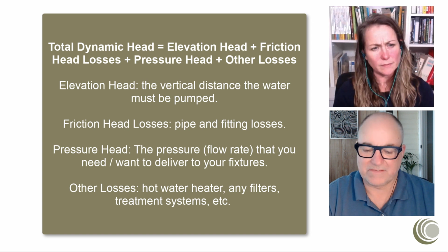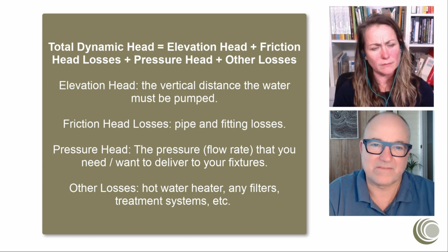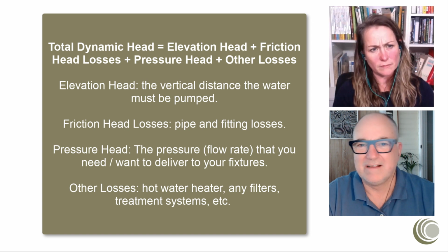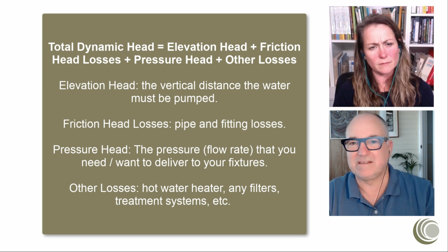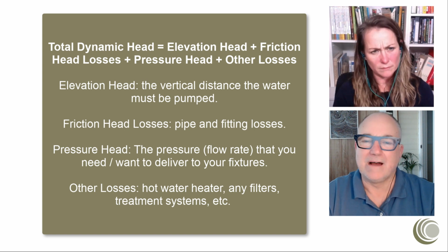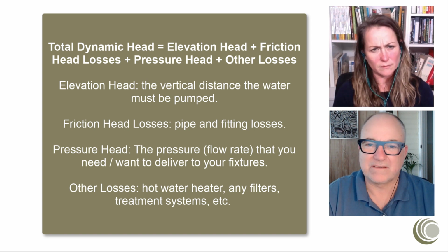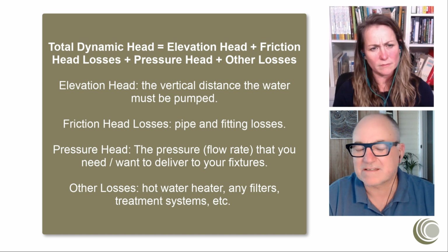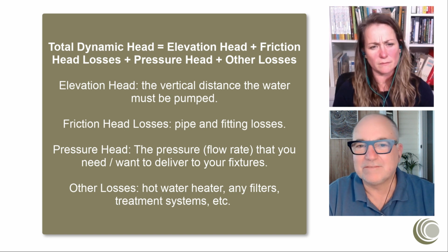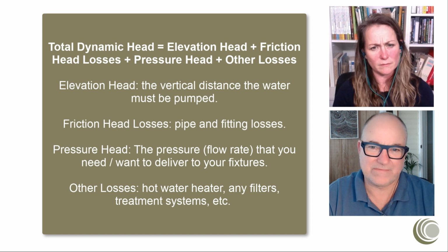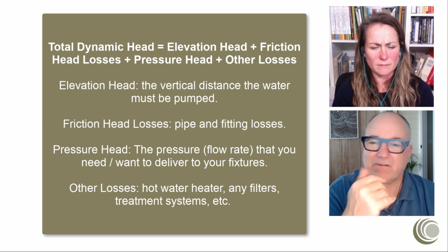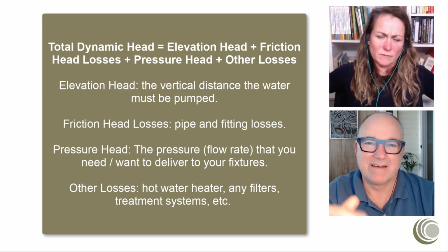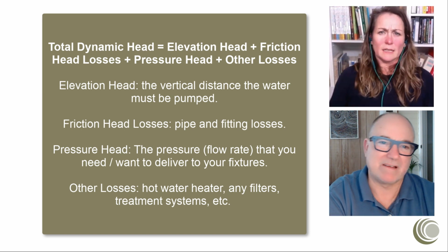Yeah, say you've got a garden variety pump that will give you 30 meters or 100 feet of head, but throughout your plumbing system, because of bends and friction losses, you lose 10% of that. You're down to 27 meters, if my maths is right. And if the highest supply point that you need to lift the water up to is 10 meters above it, you're probably going to be okay.